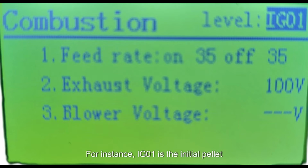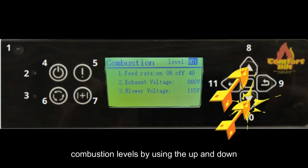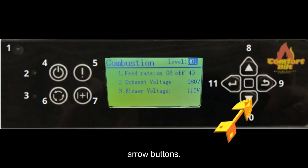For instance, IG1 is the initial pellet feed phase to prime the burn pot while the igniter gets warmed up. IG2 is the heat transfer phase, and it is during this phase that the fire usually establishes. You usually want to have a slow trickle of feeding on this level, but not too much that it snuffs out the small fire. IG3 is the holding pattern phase. It keeps the fire fed and growing until the internal heat reaches the threshold for it to enter the heating phase. You can scroll through each of these combustion levels by using the up and down arrow buttons.